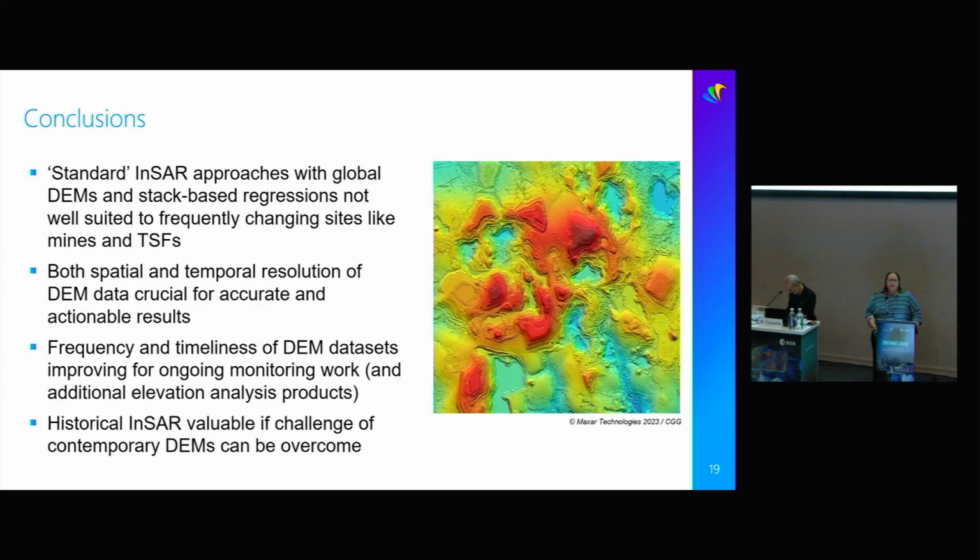But in conclusions, we mustn't forget, I think, that the standard InSAR approaches with a global DEM and a stack-based regression don't always suit things that are frequently changing or have really fine-scale topography, for example, urban applications. And whatever we do with the decisions we make in the future for SAR processing, for example, and SAR data supply, needs to bear in mind the fairly specific needs of these kinds of applications.